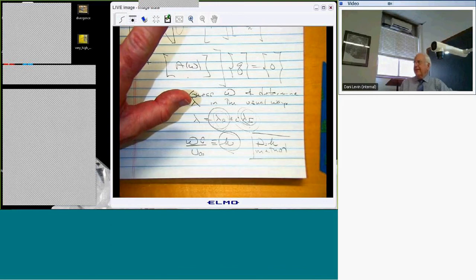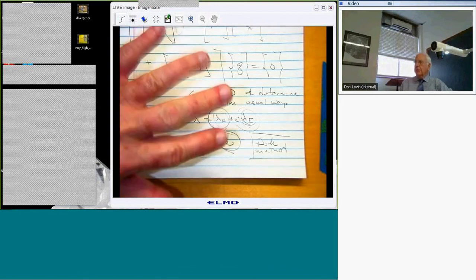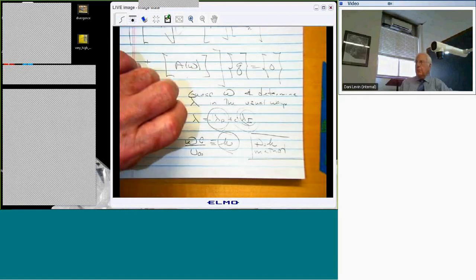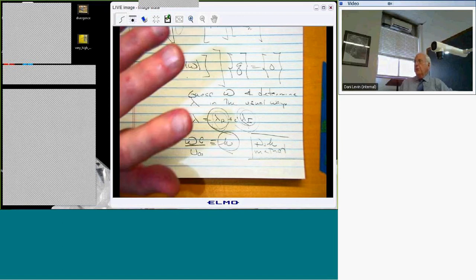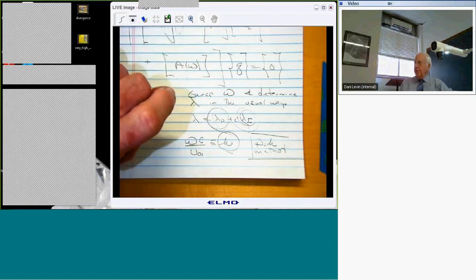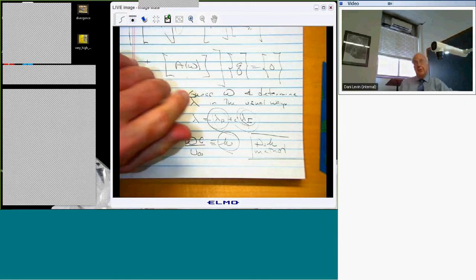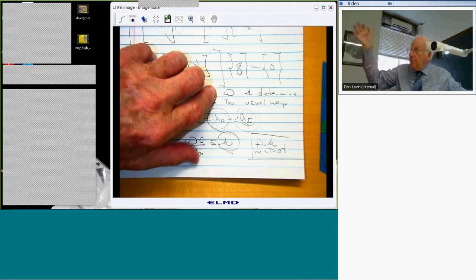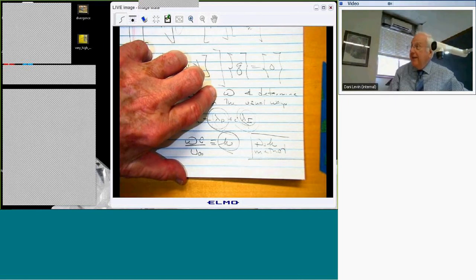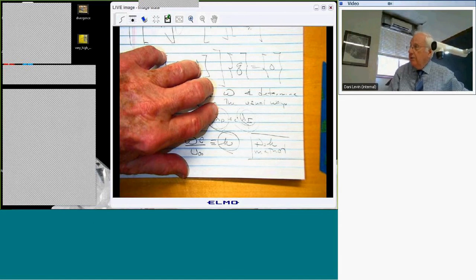So you're forced to a somewhat convoluted but effective way of finding the flutter point. But the good news is, for piston theory and for your homework, you can do what you might normally be hoping to do. Namely, you just assume a form of the solution, either e to the i omega t or e to the lambda t, and then appeal to MATLAB, and away you go. So you should be okay on that.